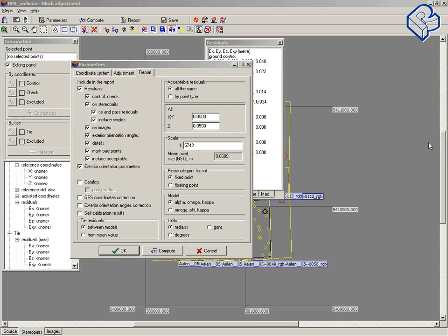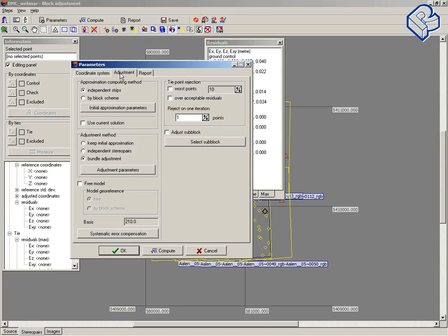From Sigma Geo from Portugal: we are having some problems when it comes to block adjustment. It always excludes one point in parameters rejected points. Is there any way to disable this in version 5.1? Why does it always exclude? Maybe you use this option, type points rejection, because only in case of this option will the solver automatically exclude some points.